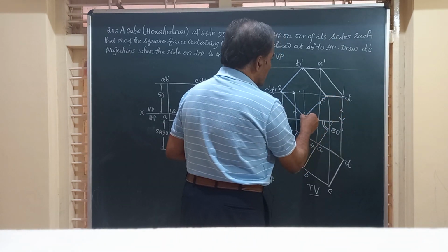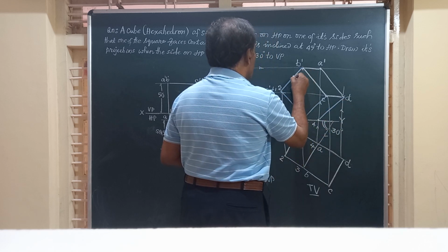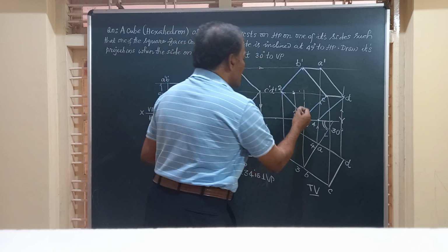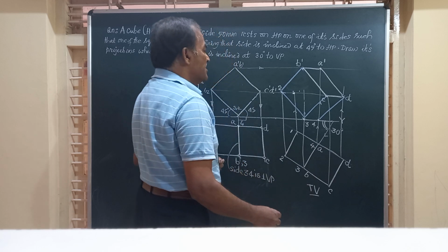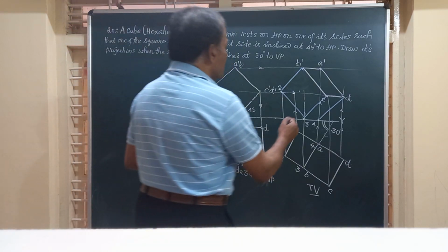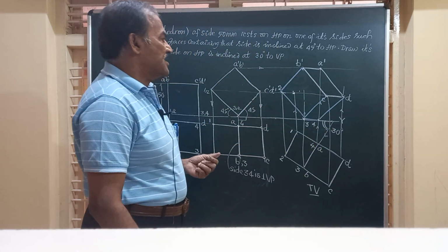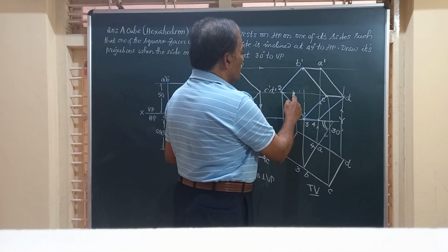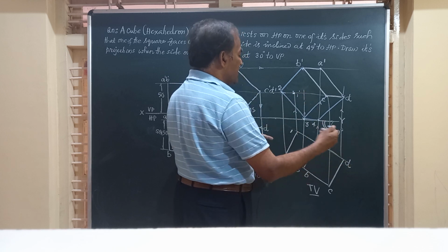C3 then D4 all are joined here, friends, and this is the top face, the other face. This is 1, 2, 3, 4 I have marked, 3 and 4 are here. Friends, if you just join this and you observe here, the square faces appear as rectangles there. And what is not visible here, friend, is the point 1. And this point is not visible in the front view.